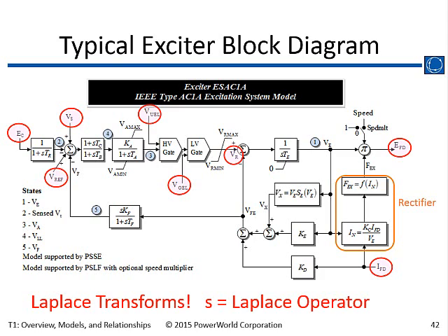But if somebody gives you a model and you're trying to figure out how come my transient stability run is not working, and somebody, rather than putting a KF there, maybe forgot about a decimal point and changed the gain from 1 to 10, and that drives your model unstable, that can be a problem. And if you have no understanding of how a block diagram works, that can be a problem.